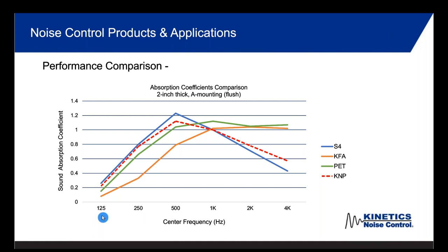The test standard C423 for sound absorption goes from 125 to 4,000 Hertz. So that's why we're only publishing that. When somebody says, well, what's the absorption at 63 Hertz or 8,000 Hertz? There are extrapolation guidelines, but they do fall out of the realm of the test standard. But what we do is we look at the space, we run a reverberation analysis, and then we determine based on cost, maybe the budget, maybe the look, and how much absorption you need, which one would be the best.